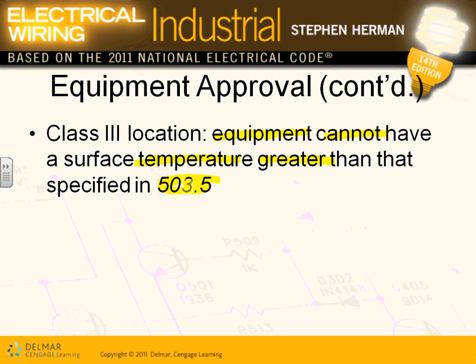For a lot of us, the most important thing, without getting into all the temperature details, is that when you look at a piece of equipment, you have to look at the listing. The equipment will be listed Class 1, Div 1 or 2, or Class 3. So the most important thing when you look at equipment is to see if it says Class 1.